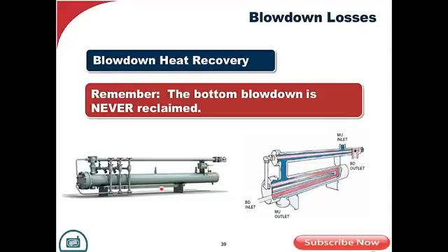But remember something. Don't ever try to recapture bottom blowdown. Bottom blow is there to be performed once or twice a day, depending upon the chemical analysis and the requirement. Goes into a separator and you waste it, because otherwise you'll foul this with sludge, and it's so intermittent. As I said, once or twice a day, the juice isn't worth the squeeze in paying for any recovery, really. So bottom blow, don't recover. Surface blow, think about it seriously.